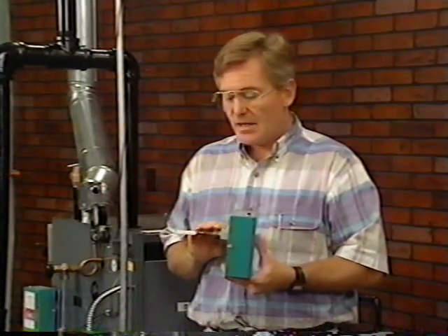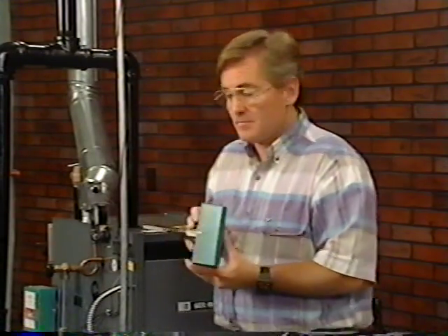This type of low water cutoff usually has a timer built into it to allow for normal fluctuation of the water level during normal boiler steam generation. This type of low water cutoff doesn't need to be flushed, since it doesn't have any place for sediment to accumulate. However, deposits can build up on the probe and allow the electrical circuitry to remain on in a low water condition. As a result, the probe should be removed and checked annually, and should be checked more frequently in a hard water condition or when a high percentage of makeup water is used.